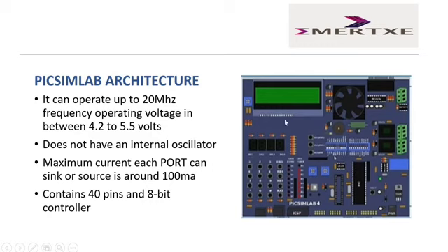It can operate up to 20 MHz frequency. Operating voltage is between 4.2 to 5.5 volts. It does not have an internal oscillator, and the maximum current each port can sink or source is around 100 milliamps. It contains 40 pins and is an 8-bit microcontroller.